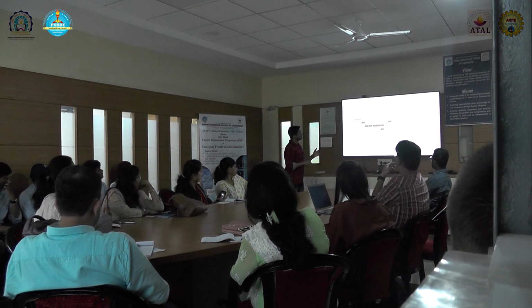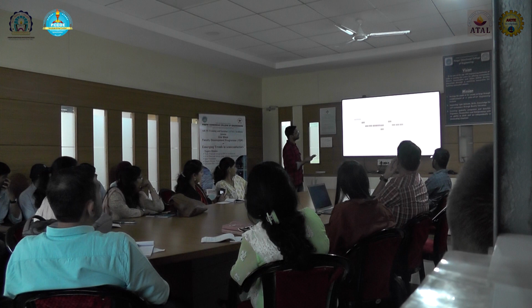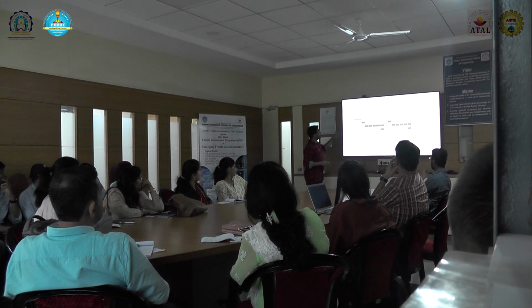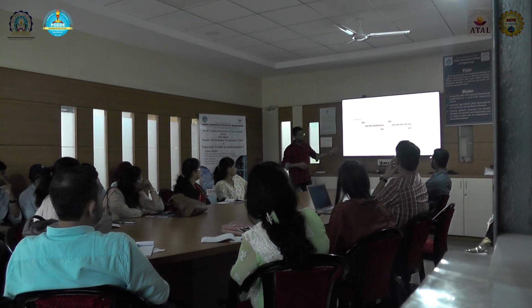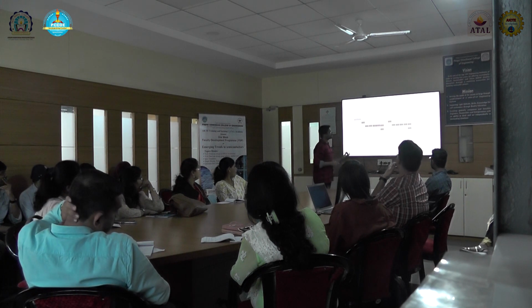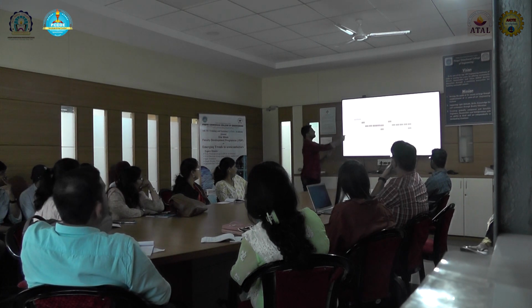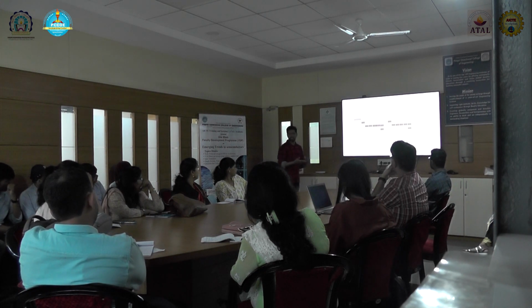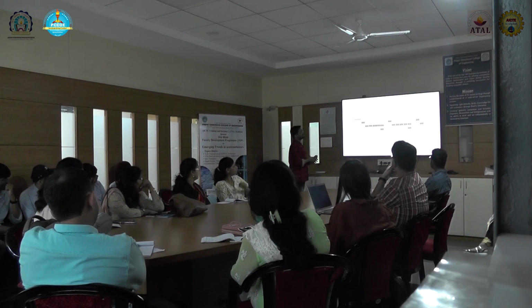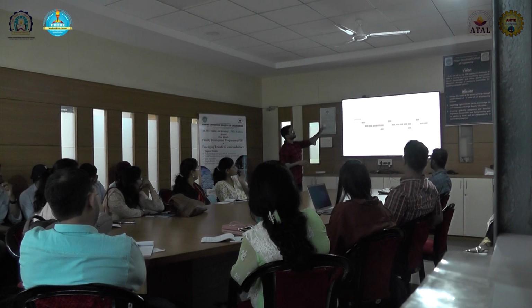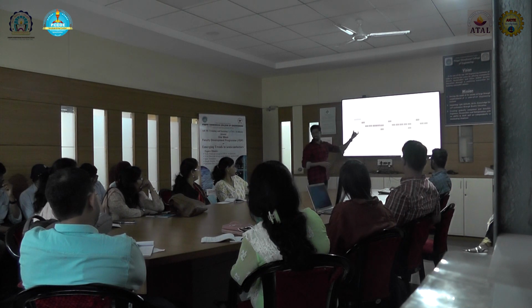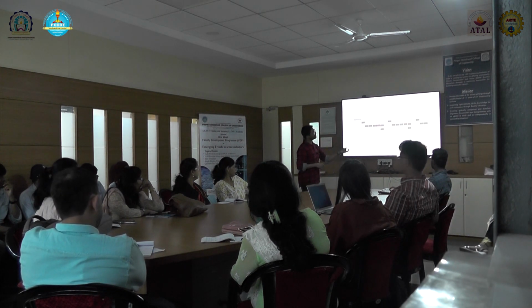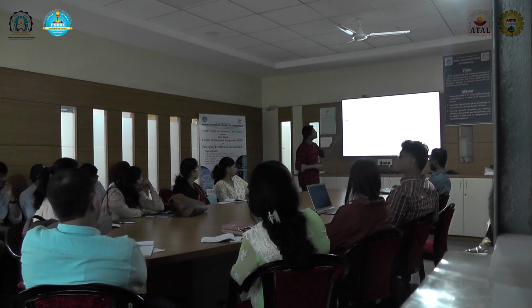Again, I am explaining one more scenario. It's not always like the green request will get done first. It's also possible that done for the yellow request will come before the green. So this is just another scenario where I am showing that both of the interfaces can get done independent of each other, and one can come before and one can come after. And this is the third scenario which indicates the earliest possible time of getting done. As you send the request, in the next cycle you get the done for both yellow and green interface, and then our main done gets high.